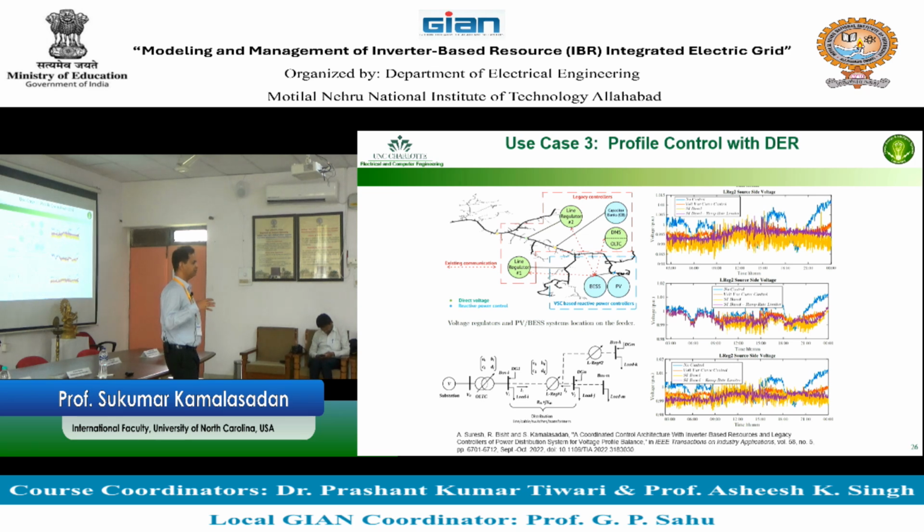There's a report coming out, not fully published. That was because IBRs connected to the electric grid at that time were actually doing constant power factor, no voltage control, and the voltage changed dynamically, and the interconnection grid tripped. So there are instances related to these two problems.